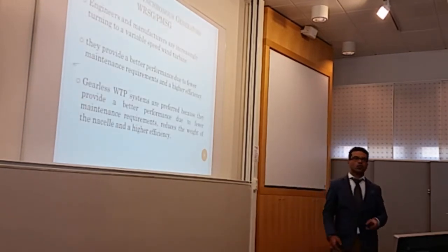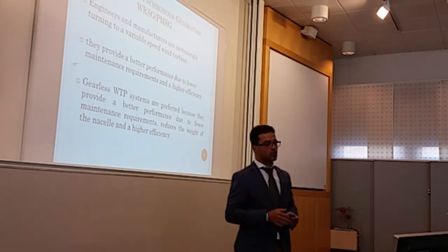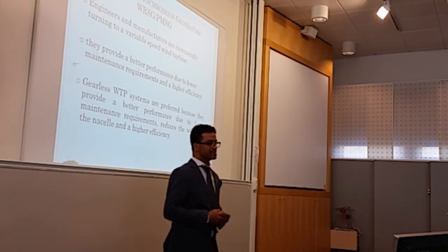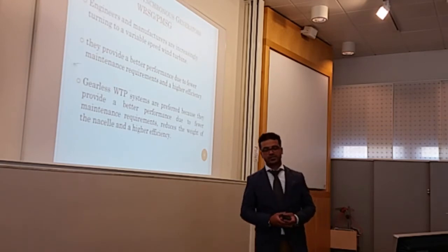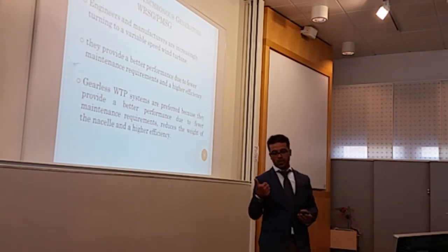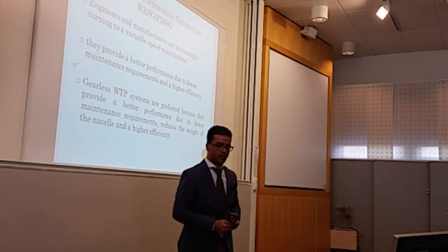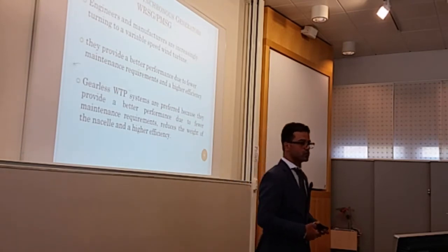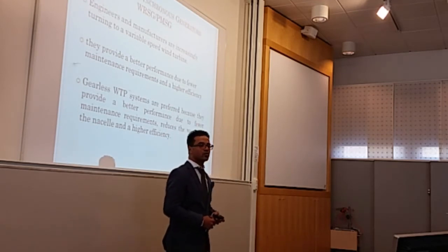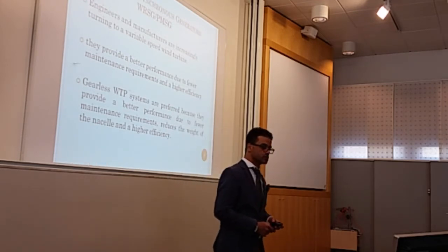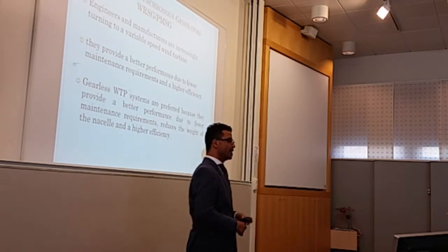Now about the generator, because as I mentioned before, the value number one is the efficiency. So we need to choose a proper generator for our system with, number one, higher efficiency, and number two, providing more power. So why are we choosing the direct drive synchronous generator, either the wound rotor synchronous generator or the permanent magnet synchronous generator? Because this system is working without any gearbox.